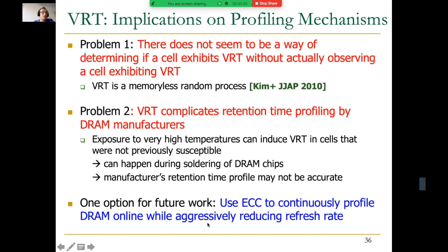And we actually have other future work that I'm not going to talk about at this point, at least. But DRAM manufacturers actually took up on the idea, and they actually implement error correcting codes today, but unfortunately not in a way that is nice, in my opinion. Because variable retention time is a huge problem for DRAM manufacturers, they added error correcting codes inside a DRAM chip, and those error correcting codes automatically correct errors that happen inside DRAM. Unfortunately, this is completely transparent to the memory controller and the system. So a correction may happen, and that correction doesn't get exposed to anyone else in the system.